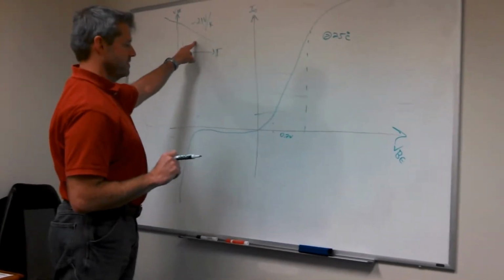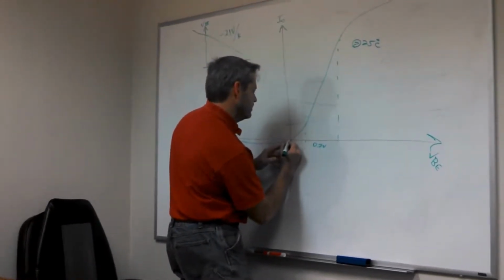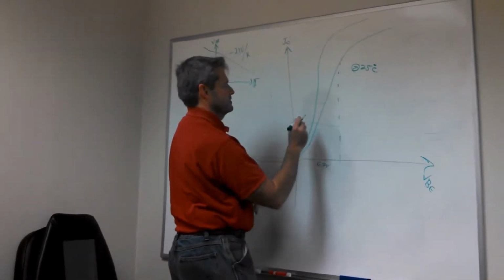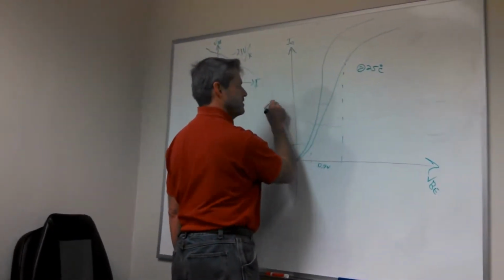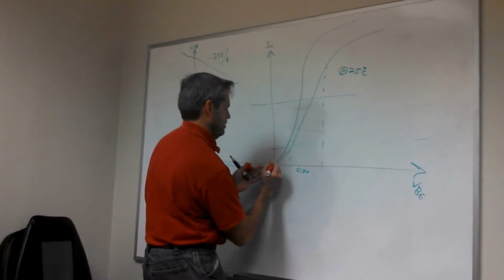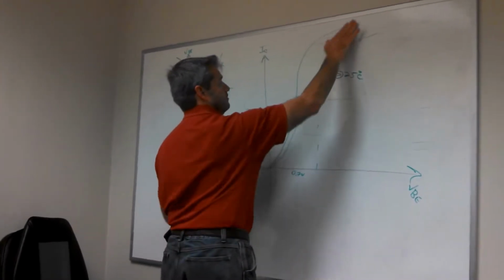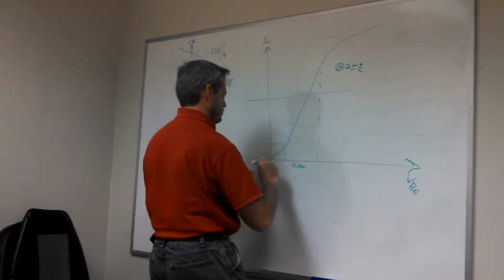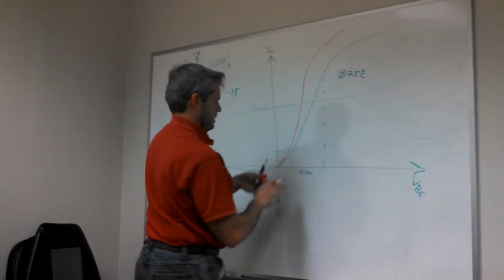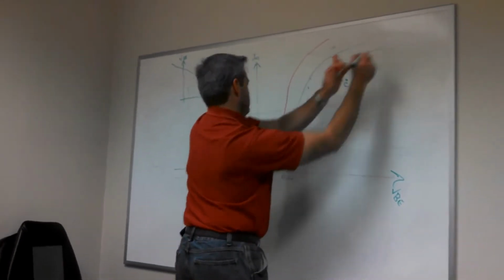So as we get warmer, that means our voltage goes down, right? This curve still goes through zero here. It looks like this. For a given current, as you get colder, VBE goes up. So we'll do it this way: as you get hotter, VBE goes down, and as you get colder, VBE goes up.